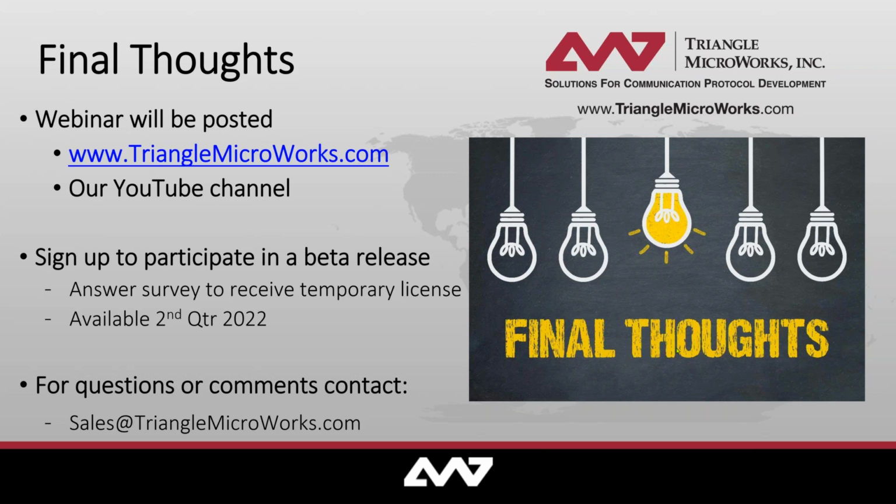We also have tools for monitoring the GOOSE stream and pulling information directly from the GOOSE stream. It is anticipated that our 61850 actions will allow you to drill down to that level at some point. They don't currently look at the GOOSE stream to extract information from the stream. But as Matt pointed out, we have the capability within DTM to actually look at the GOOSE stream, but our actions do not currently drill down and look at that. They will simply monitor for value changes, but we do anticipate doing that in the future. Sample values, I'm not so sure about. That's going to be a different challenge.